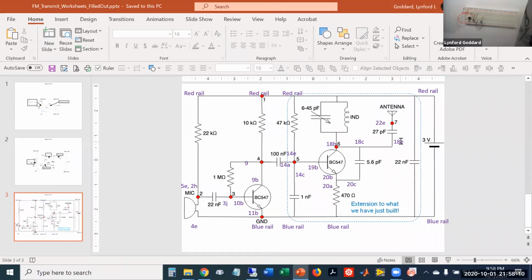Okay, so we've connected that, and while we're at 22E, we can connect the antenna. So you saw me struggle with trying to strip the wire. I think it just takes a little bit of practice. And then we want to plug this wire, this is our antenna, into 22 in one of the rows. So I'm just going to pick 22C.